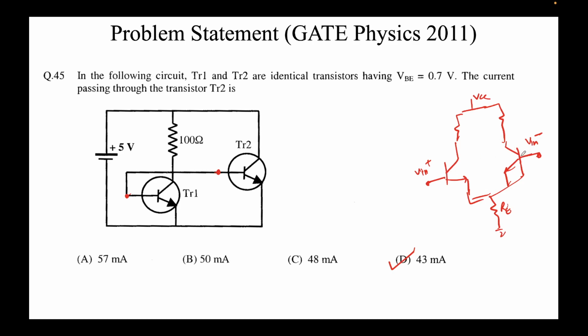They're not the same. If they are the same, that could mean we are in common mode. So common mode will look remarkably similar to this circuit, but then some resistances will play their role, yes, but its functionality would be very close to a current mirror. That much I can say. Not ideal, not exactly close, but you can follow the same process flow as we followed in case of a current mirror. Does that answer your question?